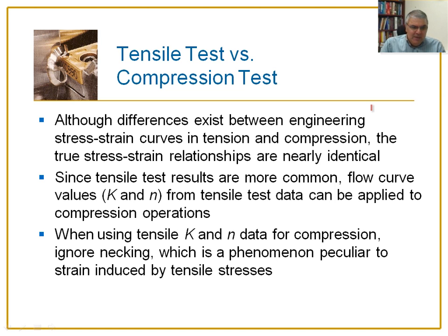When we're using tensile K and n data for compression, we ignore necking. Again, this phenomenon is peculiar to strain induced by tensile stresses.